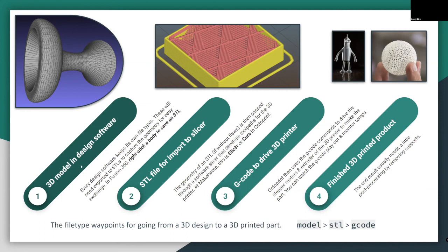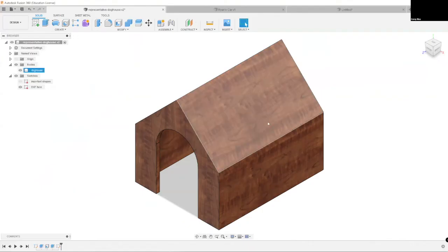So in Fusion 360, all of your files are saved on the web, and you don't even need to worry about managing the files themselves or their file types. It's great. It's another reason why I like Fusion 360. From there, you'll get an exported STL file, and I can show you how to export an STL file by just hopping over to Fusion 360.